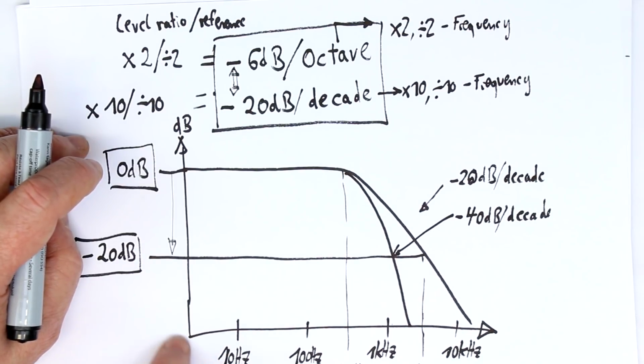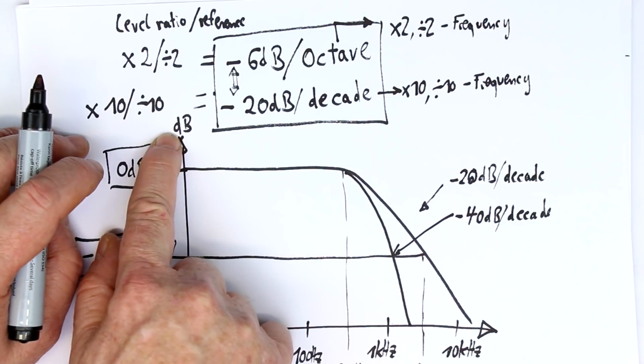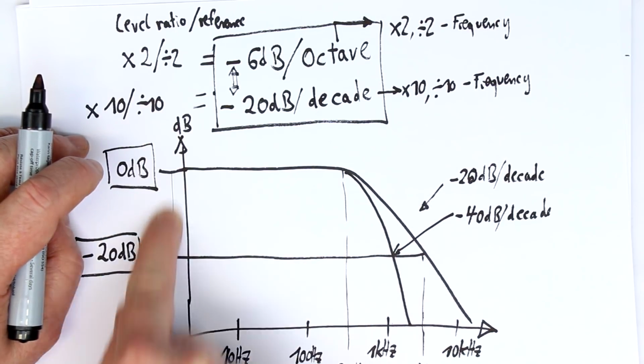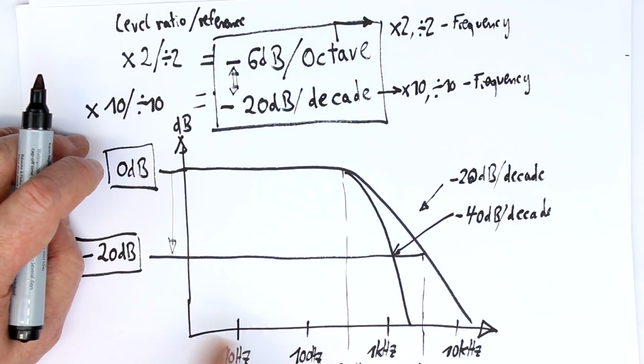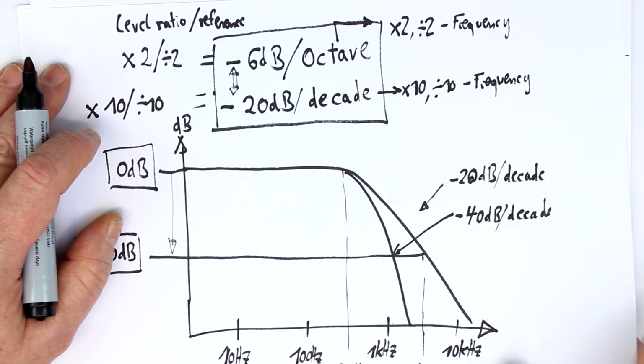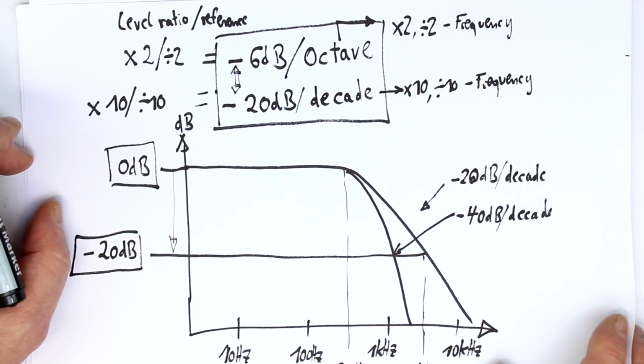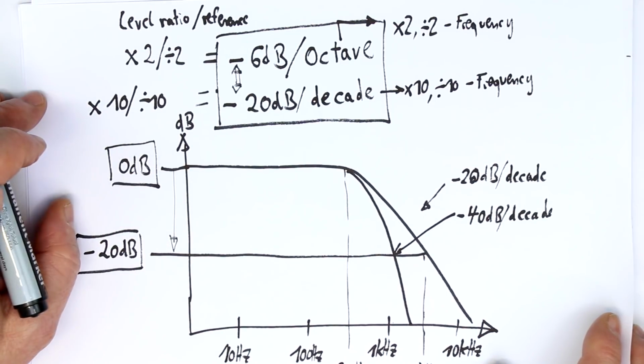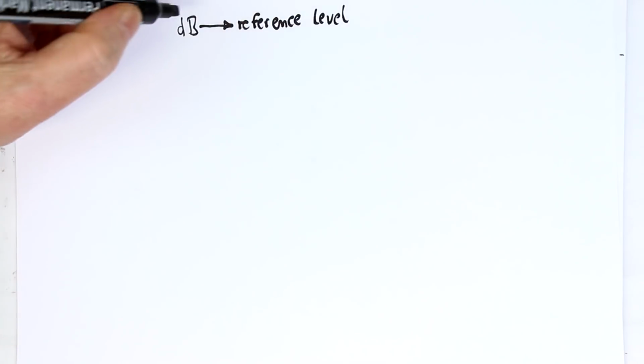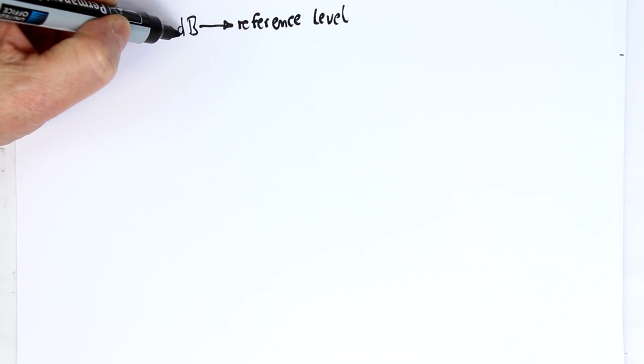The frequency scale linear, and here not a dB value, which is in itself a logarithmic value, but the measured level of voltage. So we have still one last thing, and that is that you sometimes have an extra letter behind the dB. So until now we had all our dB values because they were the ratio of two values, power, voltage or current, to an arbitrarily chosen reference level. But sometimes you want to relate your values to an absolute value.